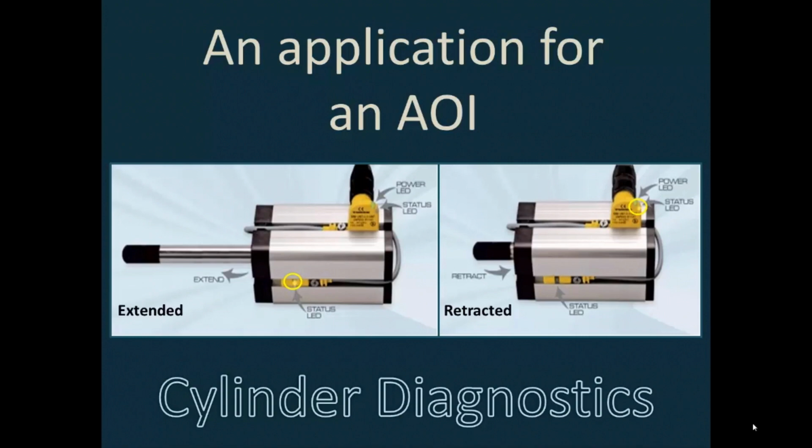If there is no external limitation to the stroke, then the stroke is going to be limited by the space inside the cylinder. In many cases, you might have a cylinder with a 4-inch stroke, but you have hard stops that are adjustable for extend and retract. That's why these sensors are mounted in, if you want to call it, grooves or channels on the side of the cylinder. So you can slide these sensors back and forth in that slot, and then tighten them, lock them down, so they actually are sensing the positions that you want.